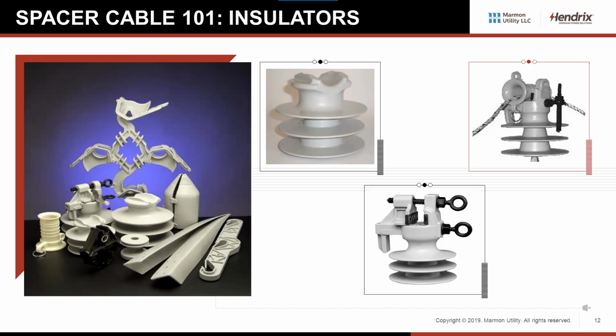The one thing that I always try to point out is, even if you are using the tie top insulator with covered conductor, we recommend using covered tie wire, because again, you don't want any bare aluminum, you don't want any steel grips or anything touching the covering of the conductor, because that'll cause the breakdown in the covering, especially at the higher voltages.